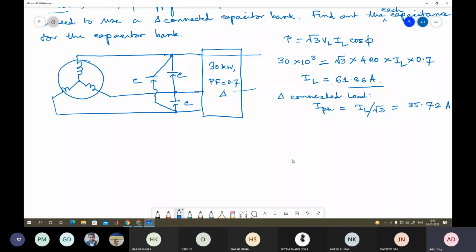So we can draw a resistance, inductance here, resistance, inductance there, between these two lines, and there also resistance and inductance, and these are all the same. Sir, the two delta connected systems are in parallel? Yes, in parallel, because this is one triangle, this is another delta. Okay, these are in parallel. So if you take a per phase kind of circuit, then this will be your per phase thing, right?